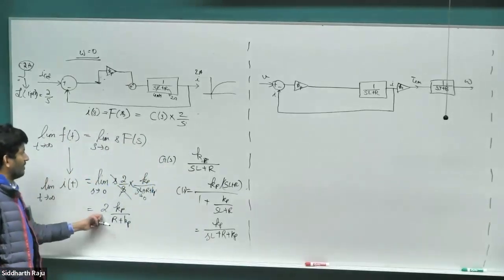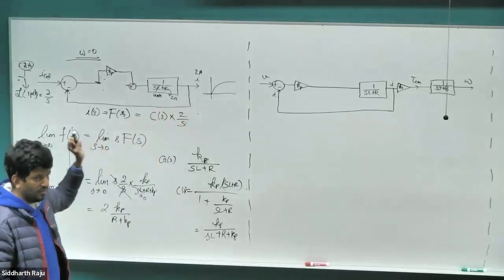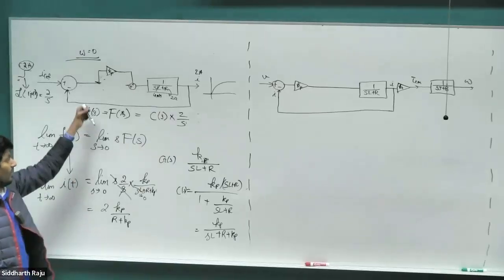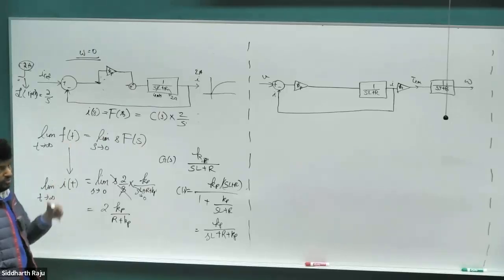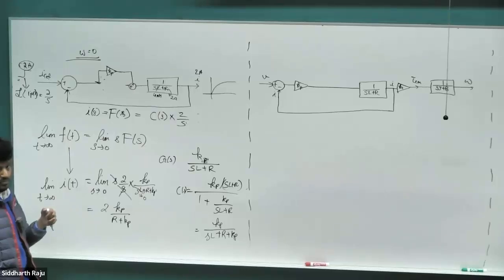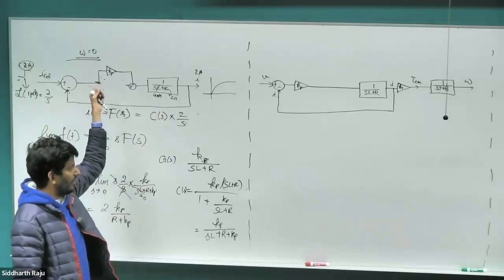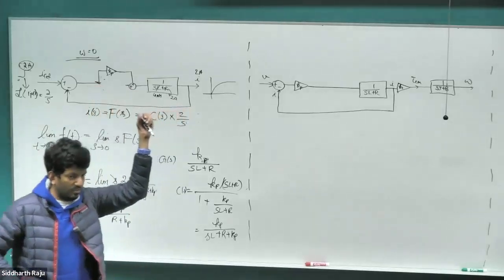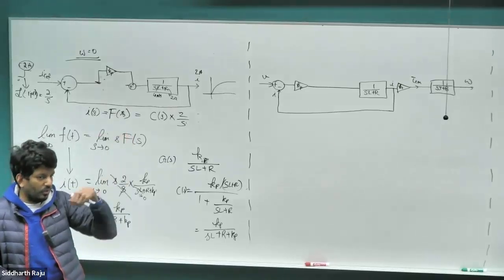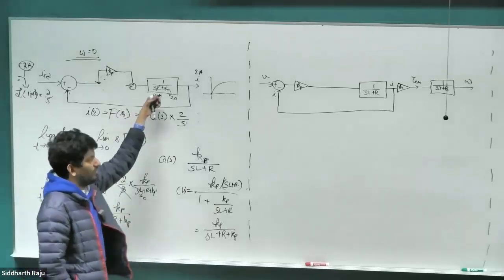In what scenario would I get the 2 ampere that I desired? With the full PI control. Without the integral controller, what characteristics should the motor have so that I get the same 2 ampere that I asked for? R is 0. The reason we added our integrator, when we looked at our car example, is to overcome the friction. If there was no friction, once you get your desired speed, you don't need to apply any force on the pedal. So it's always the loss term. In our case, the friction is the resistance.